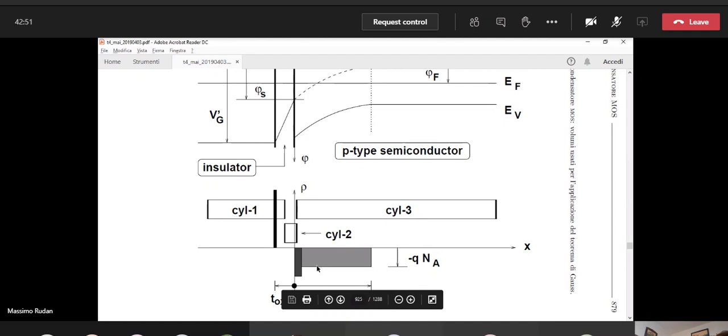And if we also remember the ASCE approximation, the abrupt space charge edge approximation, we assume that there is a discontinuity of charge. We go abruptly from the space charge region where the concentration of charge is a non-zero constant, okay, to the neutral region where it is zero.